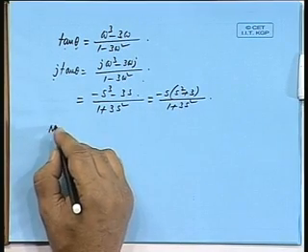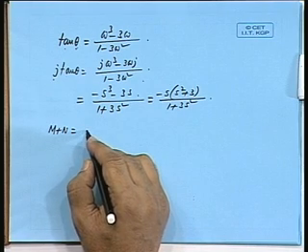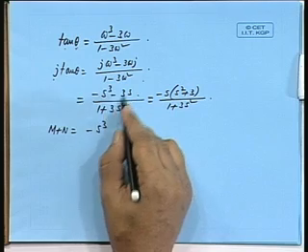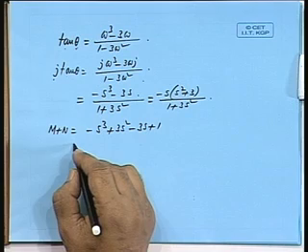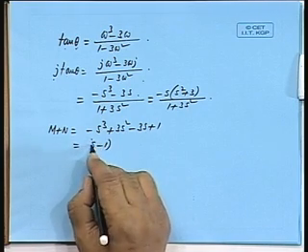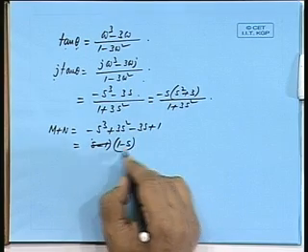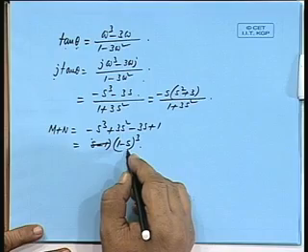So, what is m plus n? What is m plus n? Minus s cubed, just add these two, plus 3 s squared minus 3s plus 1. So, that gives me 1 minus s whole cubed. Is that all right? 1 minus s whole cubed. So, where are the roots? All on the right half of the plane at s equal to 1.